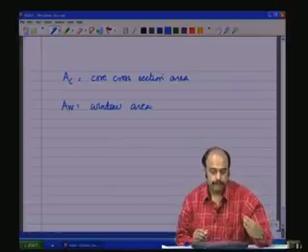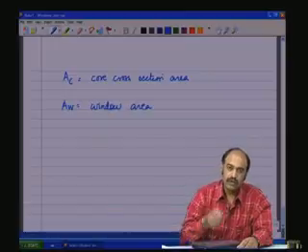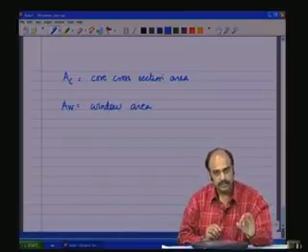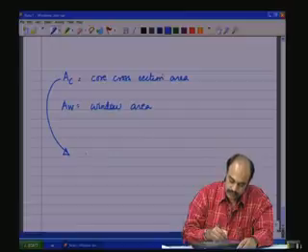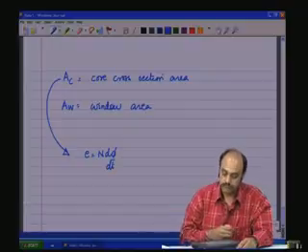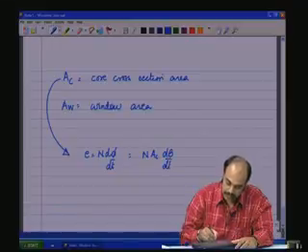These are the physical dimensions of the core. How will you map these physical dimensions to the electrical property? One is by Faraday's law. So, this is linked using E is equal to N d phi by dt, this is Faraday's law, this we know, which is equal to N AC dB by dt.